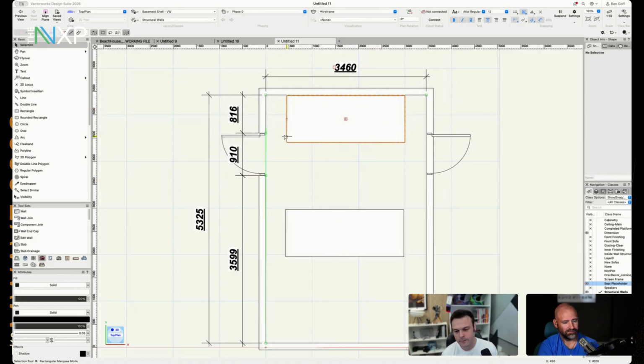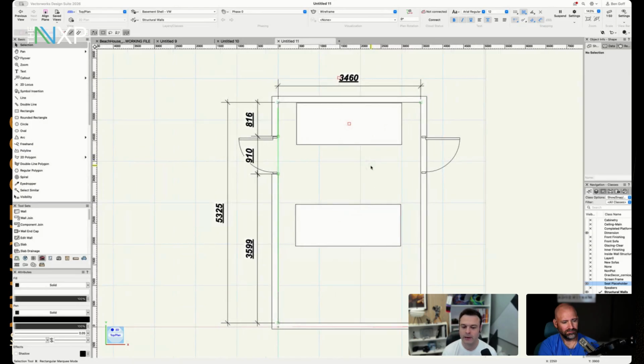But as you say, there's realistically two places in a room where we're never going to put speakers. No matter how big the channel count gets, there's two places that speakers just aren't really going to go. And they're not going to go middle of the back wall, because a center back is fairly rare. We might want a sub there, but it's unlikely we're going to want a main channel center back. It's not particularly done anymore. So that's one spot where, if you can have the door center back, it's not going to interfere with any speaker placement you want. The other is going to be between a front wide and the first surround.